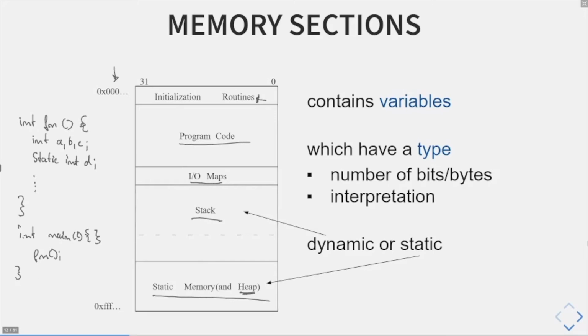And what you see here, that's a C program. If you compile this with a compiler, it will translate this stuff that I've written here into an assembly language, so into a stream of instructions that can jump around and that you can execute and then load into the memory address. So this will be translated to assembler, loaded into a program memory. And then once we reset our CPU, the initialization routines actually initialize the hardware and then start to execute this program instruction by instruction by instruction.